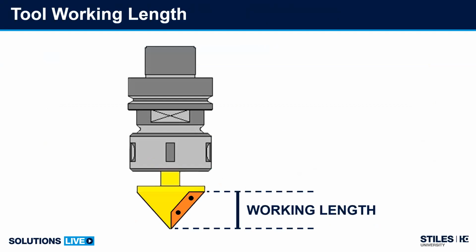So let's talk about how we protect ourselves. When you set up your tool, it's going to ask you for a length of the tool, that's the total. It's going to ask you for a collision length. For most of these applications, the collision length is the bottom of the tool where the tool's cutting. It gets a little more involved when you're talking profiling tools. But the working length is how much geometry do you have to work with. So if you don't set the working length correct, then the NC generator loses the ability to help protect you.